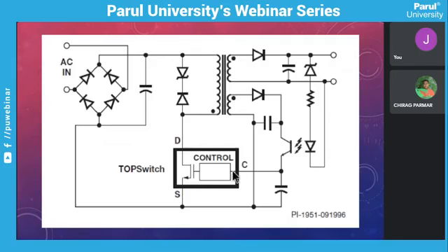At that moment, depending on whether the voltage has dropped or risen, the controlling IC controls its switching actions based on that. So this is how the auxiliary powers the oscillator and the feedback of the SMPS. So this is in general a controlled system. It has very much benefit compared to the old power supplies we used, and this is generally used in all of the embedded systems we incorporate today.